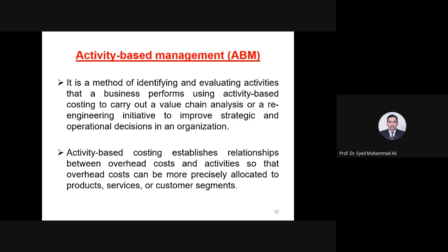So they have certain activities. Now, very consciously, Hassan is working on activity-based management. So he has divided the surveying process into various activities. For example, setting up of the benchmarks. For example, the recce survey. For example, ground truthing at the end when you prepare some sheets digitally. Then you move from one side to the other side, and so on. Then you do the sounding in the river when there is a water body.